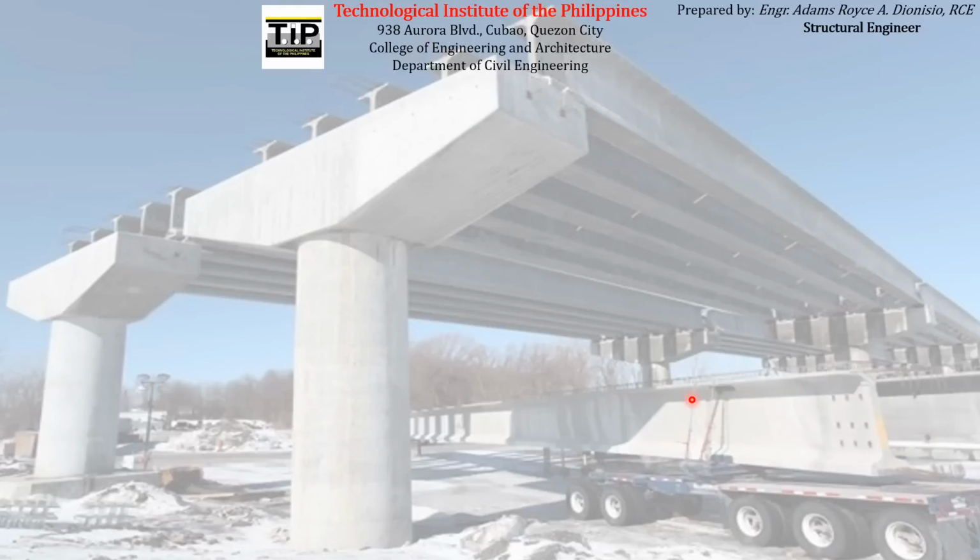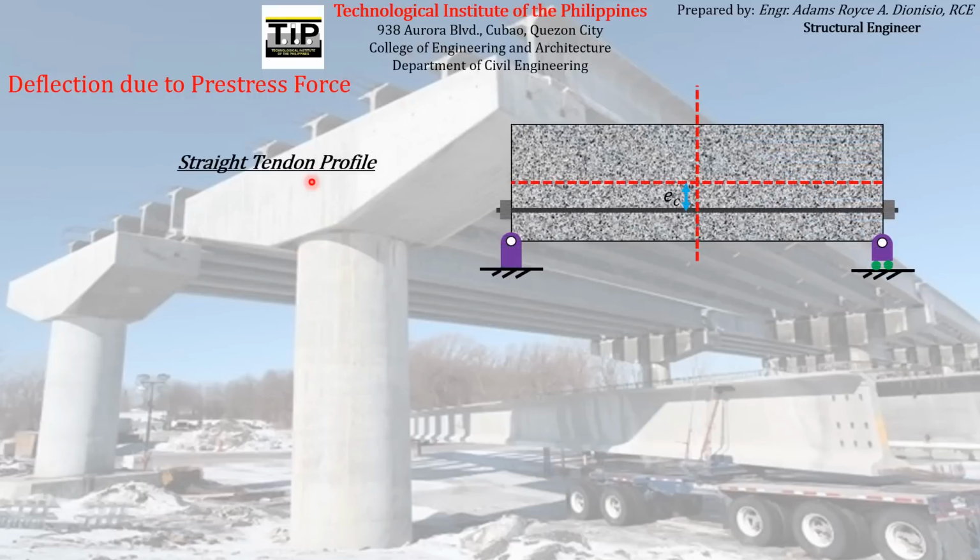For the computation of the specific magnitude of deflection, we can use these formulas that we will enumerate here. For the computation of the deflection due to the prestress force alone, say for example, if the tendon profile is straight like this, the maximum deflection that will be experienced by a prestressed concrete beam with a straight tendon profile is equal to this. Actually, the maximum deflection will occur at midspan.